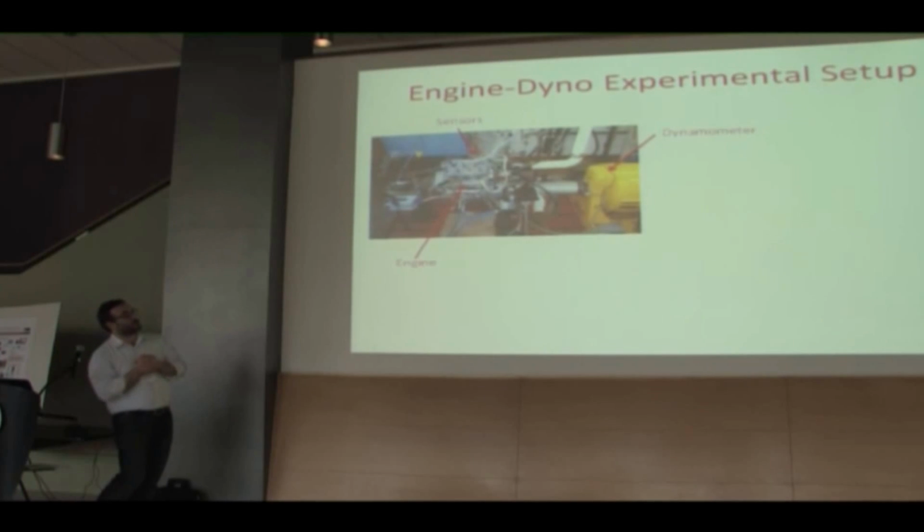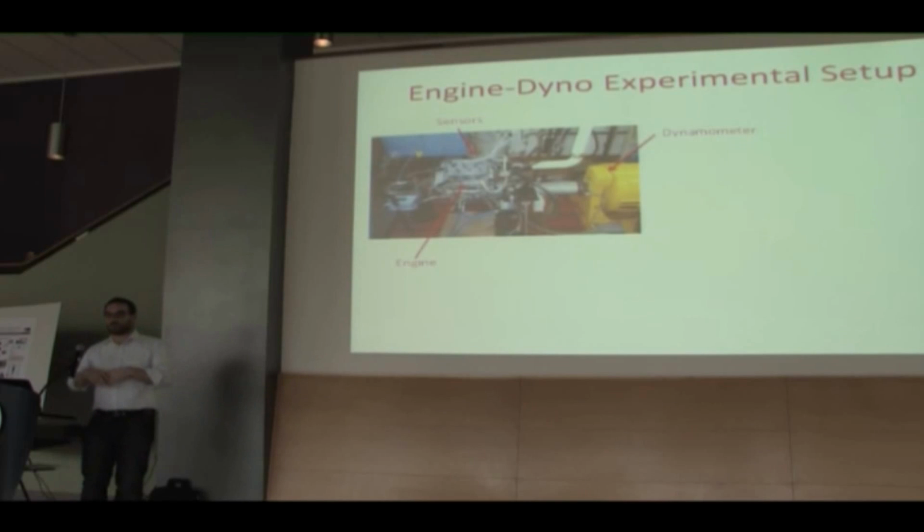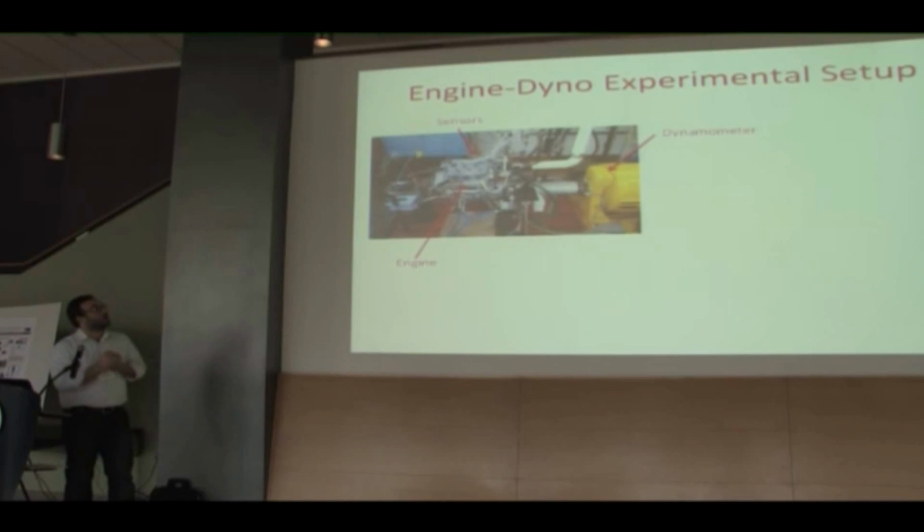The meter measures the force. Basically, it brakes the engine, doesn't let the engine speed up, and you can measure how much power it's generating. And of course, you need a whole bunch of sensors, all these cables, wires that you see there. They connect to thermocouples and pressure transducers and so on. But this is not just it.